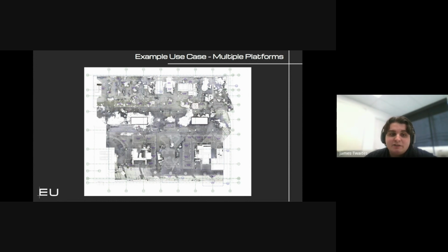So what you're seeing now is a slab plan that is the actual slab as built. Every pixel on that is basically a point from a total station. And where you don't see data, that's because the scan was blocked or there's no slab to scan. So those two large rectangular openings in the middle, that's real. Those really are openings. But then you can also see that there's white space inside the cores where it's blocked by walls. And those blotchy areas with the rougher edges are puddles, which reflect lasers, so those areas don't show up in a laser scan.